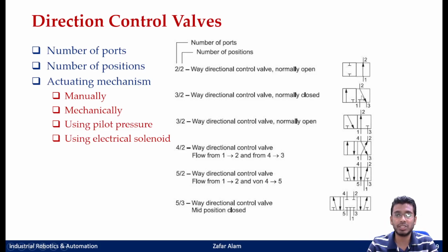So for example, if this valve can have two positions, what is the default position of the valve? Wherever I am drawing these two blocks, the number of ports on both these square boxes will be the same. So if the left hand side compartment has 3 ports, the right hand side compartment will also have 3 ports. Only the connection of the ports will differ between the two positions of the valve.